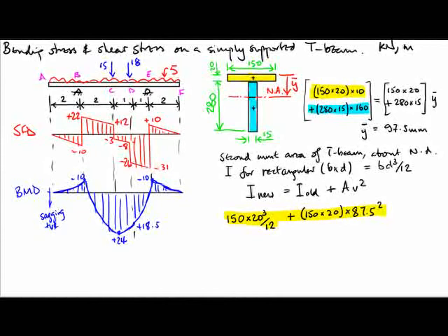So we also need the equivalent for the blue block. So BD cubed over 12, the breadth is 15 there, the depth is now a big 280, 280 raised to the power 3, BD cubed over 12. Just notice when you turn the block around and you've got the much greater depth, how that has a much increased effect on your I value.